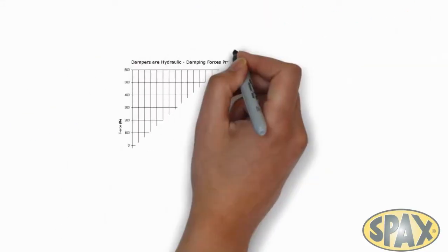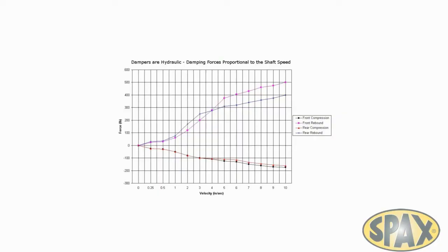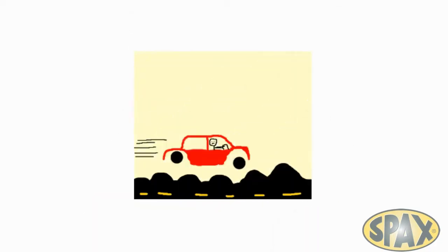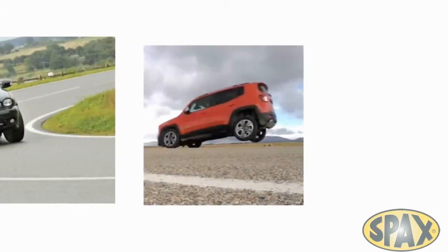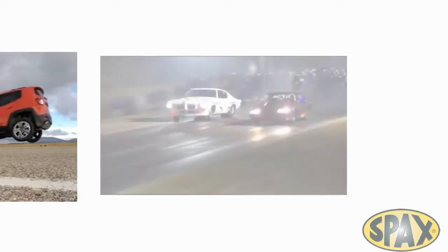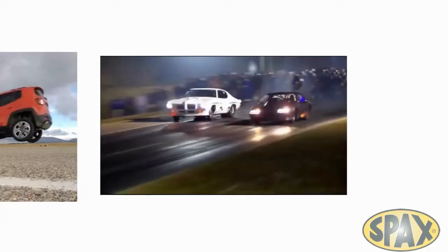Dampers are hydraulic in operation and will react to the velocity that hits them. If a car is being driven quickly and hits a bump, or slower, hitting a larger bump, then the damper shaft is driven at high speed, producing increased damping. If the shaft speed is lower, as the car is driven at slower speeds for example, less damping will be produced. Dampers are not just employed when a car hits a bump in the road. If the car is turned, brakes or accelerates, then all these actions will create consequential spring action, all to be damped.